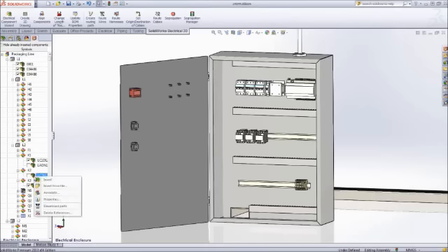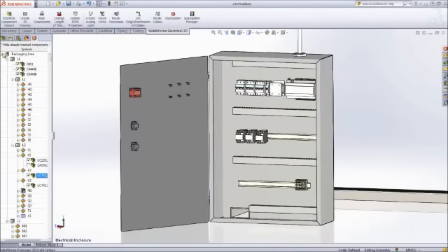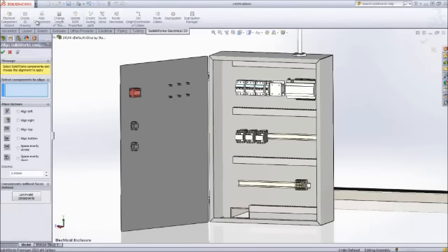The remaining electrical components can be positioned very quickly using SmartMates, or can simply be selected as they were previously placed. In fact, creating the electrical panel with ducts and rail, or wiring all the components can be done very quickly with the numerous intuitive tools that are included. The Align command, for example, lets you space these contactors precisely on the DIN mounting rail.